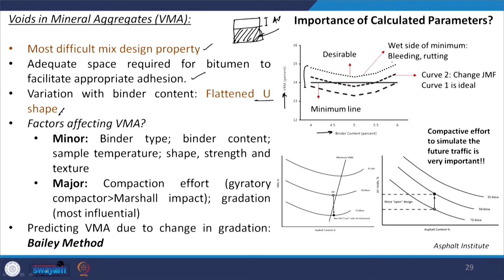So, therefore, with increase in binder content, since we are reducing the individual voids between the aggregate particles by allowing them to move or occupy a more dense space, the VMA will reduce because the voids between them are reducing. Well, if you keep on increasing the binder content, beyond a particular value, this binder which is now filling the voids will become so large that it will start separating the aggregate particles rather than allowing them to position themselves in a dense space.